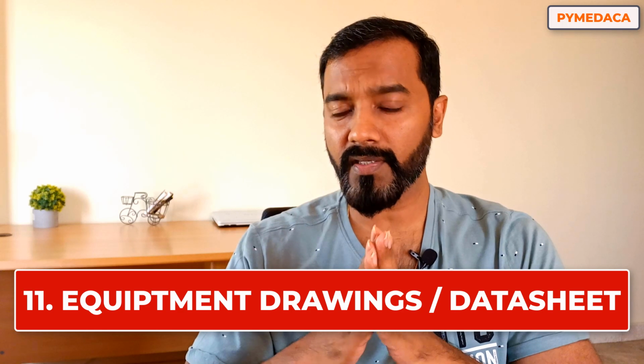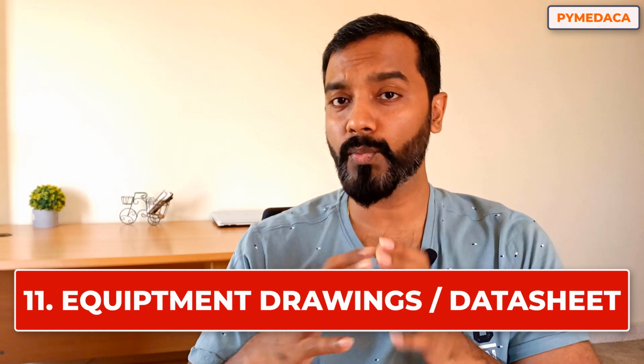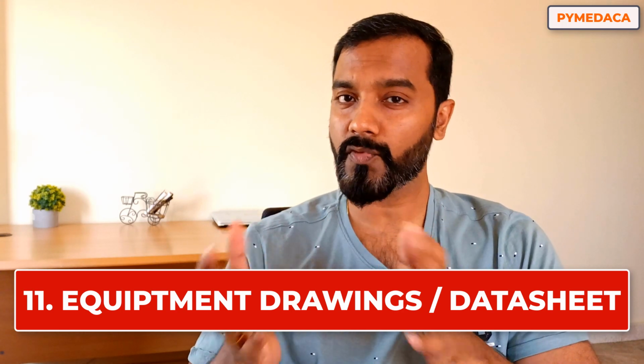The next important thing is the individual equipment details or drawings. Especially when you're starting a project, you may not have the individual equipment drawings. For that, you will have to go with a reference. For that also, you need to get the process details. You will be able to find reference equipment drawings from any previous projects or drawings that are generally shared by the static engineers. From those details you can go ahead, or they will provide you a schematic equipment pressure vessel drawing that will show you the elevation, nozzle size and overall diameter of the vessel.